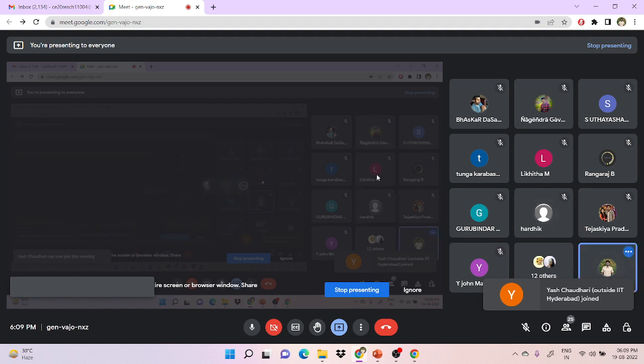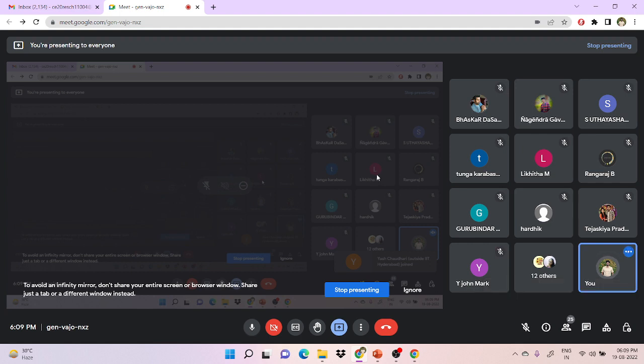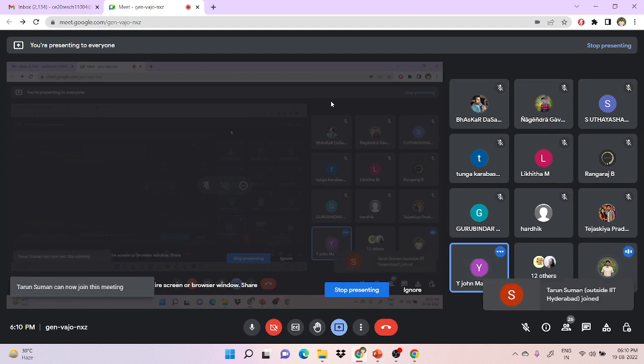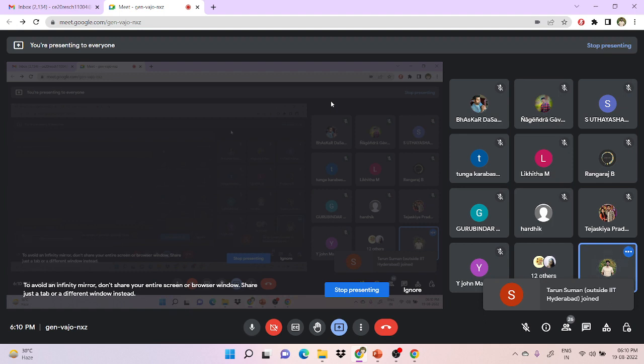Okay. Anyone else? Any other student wants to add anything? Whatever Hardik said, it is correct. Anyone else? BOD is an aerobic process and COD is an anaerobic process. COD is a chemical oxygen demand, so it's not anaerobic. Yes, sir, we use chemicals like potassium dichromate. Yes, so you cannot say that it is anaerobic. You are chemically oxidizing it.